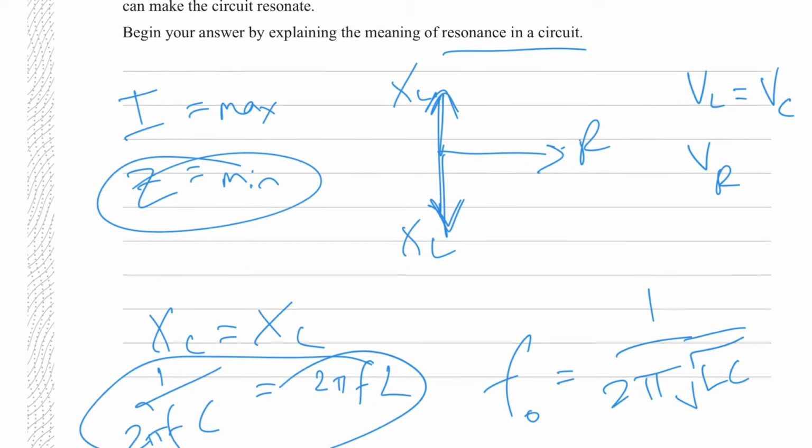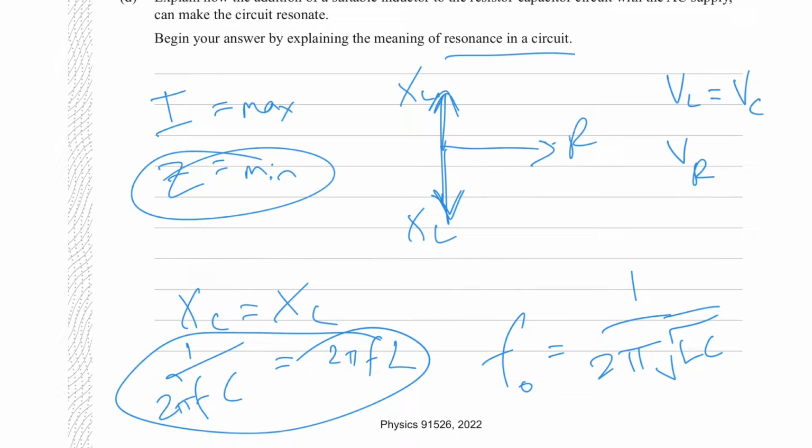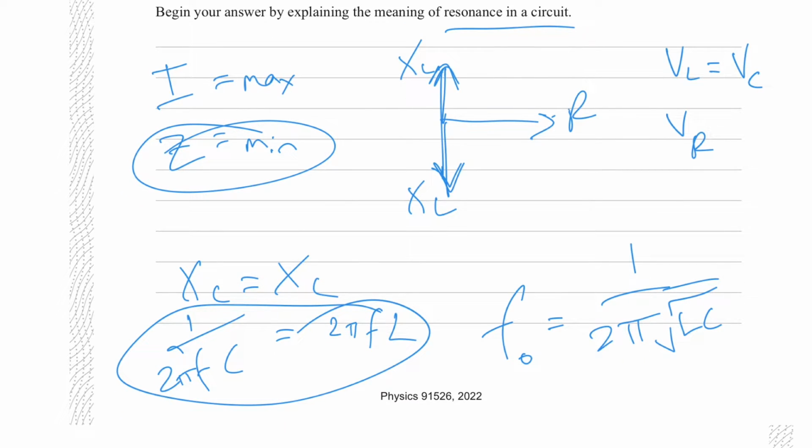So yeah, a classic application is a receiver circuit, like in a cell phone or a radio, anything that transmits and receives wirelessly. In your antenna, you want to tune it to a particular frequency to maximize the signal that's coming in and to cancel out all other signals, because there are so many different signals waving around through the air. You need to be able to amplify the one signal you're interested in and convert that to sound or a person's voice on a phone or whatever it may be, your internet signal.